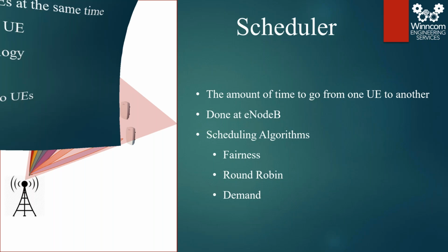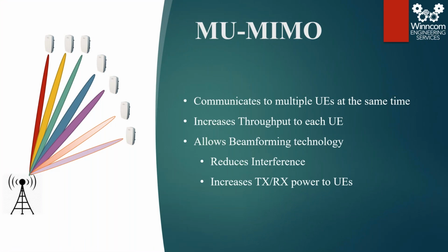So in the last slide, we were talking about beam forming, and it comes down to a 10-degree beam. I had a question about 2 weeks ago: what happens if I have 5, 6, 10 houses in that 10-degree beam where the beam forming is? In that case, the beam forming is not going to be able to pick out one particular house. That beam is going to have to start going through the scheduling to communicate with those several houses within that smaller degree.